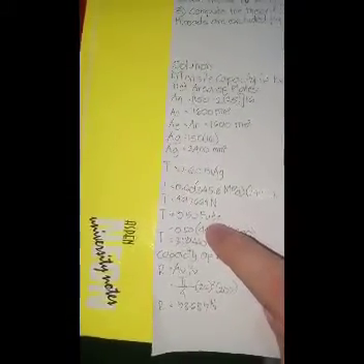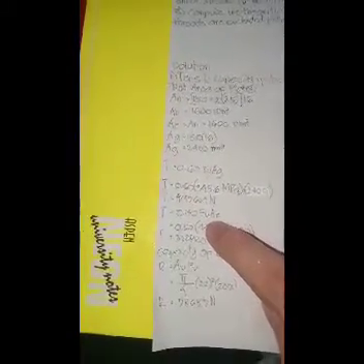Then for 0.50 times F sub u times A sub e, our answer is 359,440 Newton.